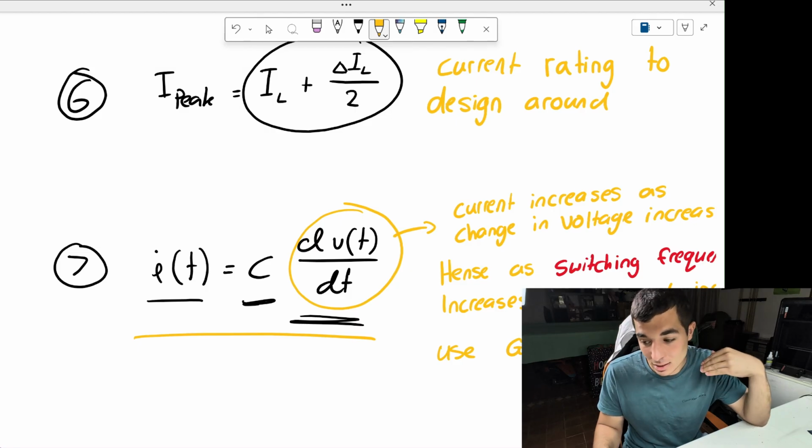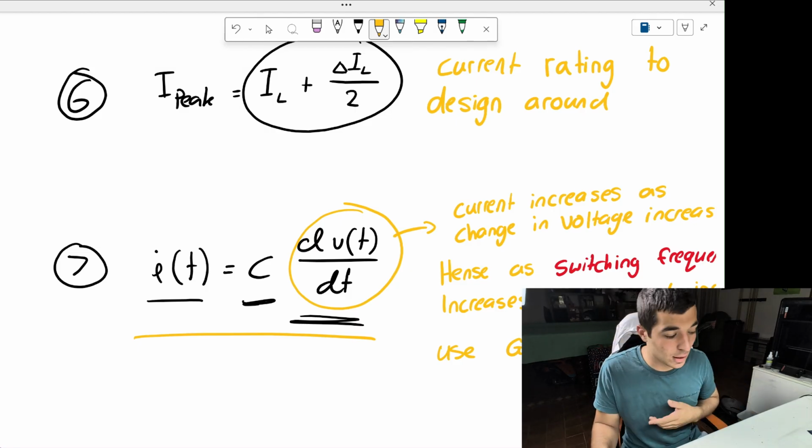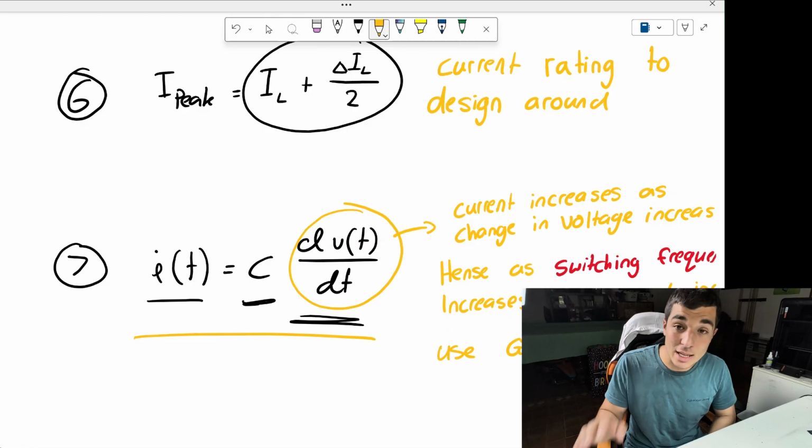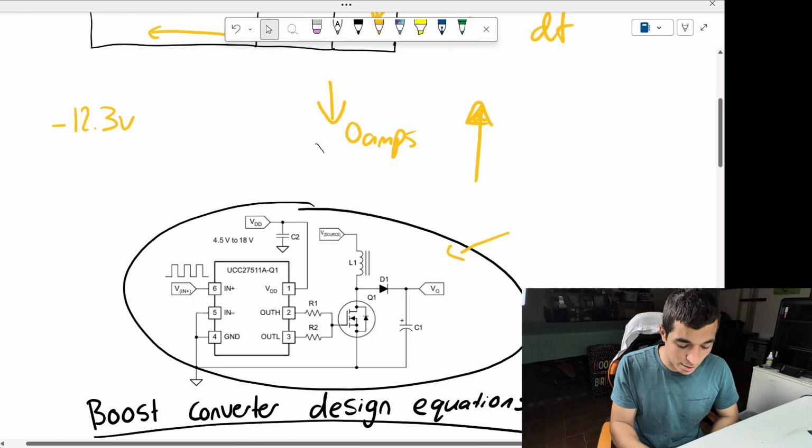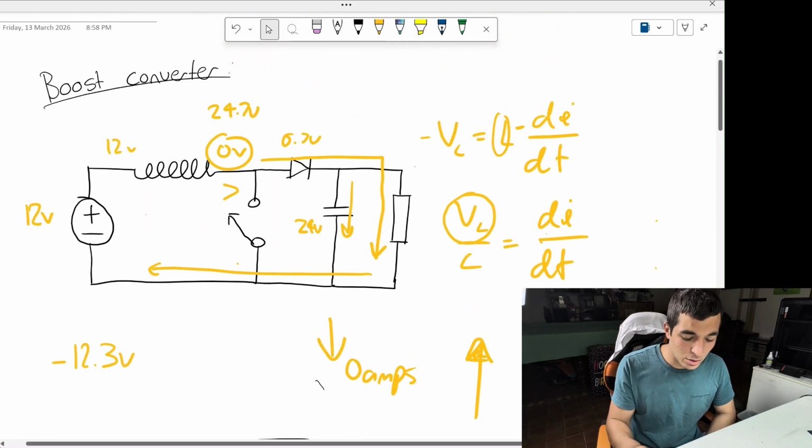Killed the board instantly. Killed the pin instantly, actually. The board was actually still working. So get a gate driver, which is the moral of the story. Also, I want to point out, you always see schematics like this.